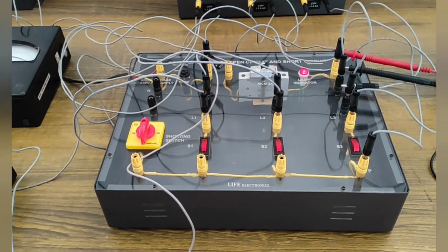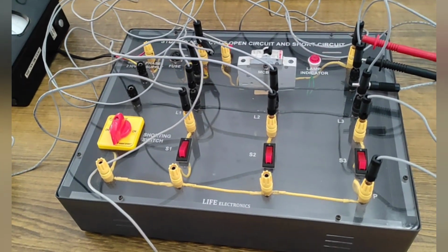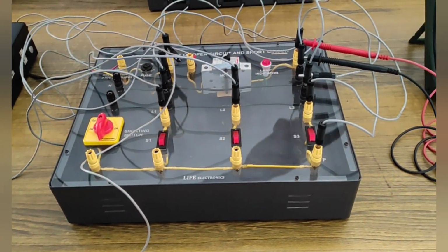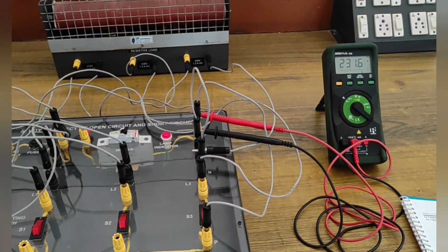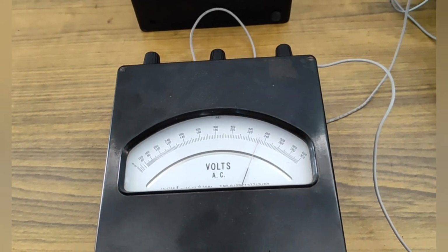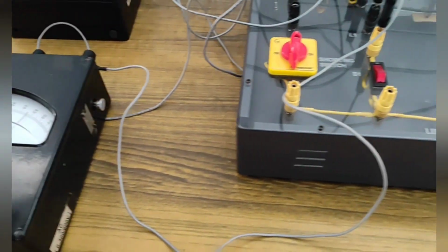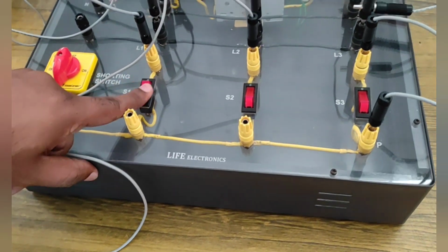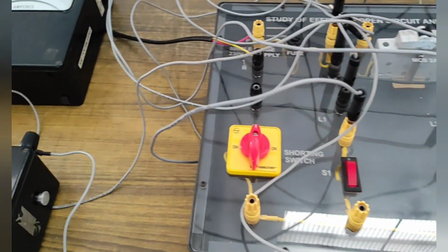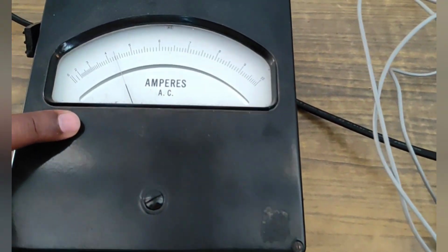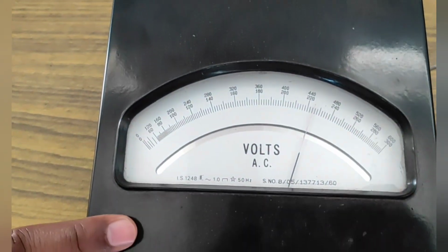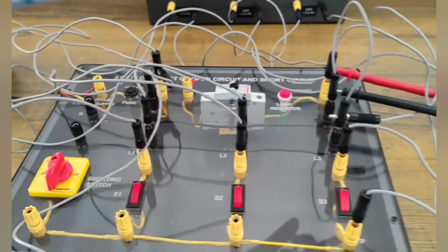So here is the short circuit with applying the load. Here the supply voltage should be on, the MCB should be on, and then it will show some output voltage, and also here there is an input voltage the same as 232 volts. With applying load means we need to apply the load by switching on S1, S2, S3. So at this time we need to note down the current, that is 4.5. It is the short circuit current. The input voltage should be 232, and the output voltage we are getting is 220 volts.